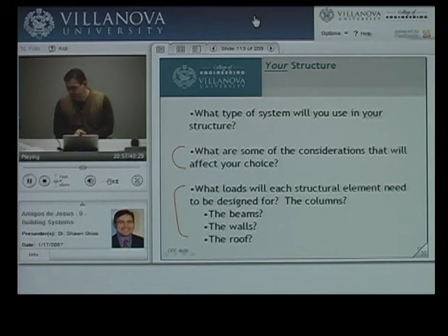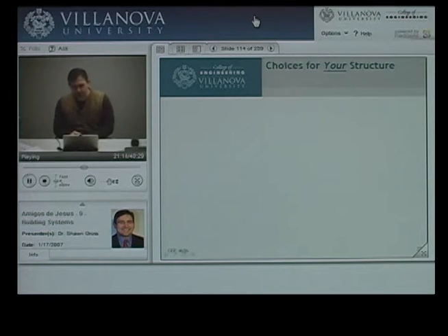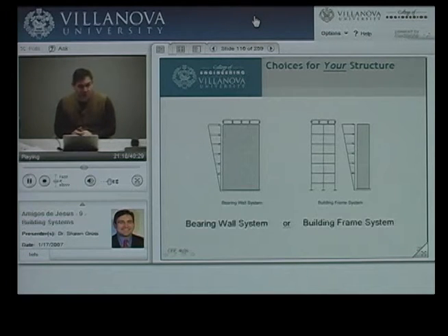Well, I gave you 4 different systems, and we have had a couple of different lectures available to you on typical construction practices, a whole lot on the history on the site. So we can actually boil it down for you to 2 basic choices for your structure. And we're going to give you 2 choices on the basis of what is realistic to be done on the site. We know we're going to be using some form of masonry and some form of concrete construction. So we're going to allow essentially one of 2 systems to be chosen, either a bearing wall system or a building frame system.